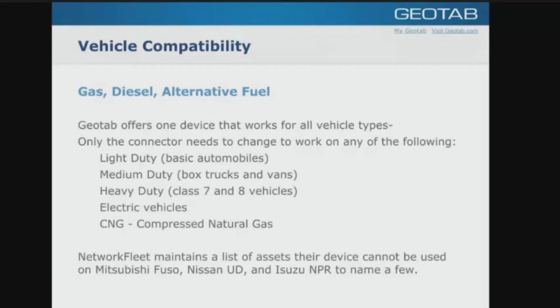These Japanese makes down here at the bottom, Mitsubishi Fuso, the Nissan UD, and the Isuzu NPRs and all the flavors of the Isuzus, they're Japanese-built vehicles. They talk in a different language. You have to decode that language to get that information. We have found, and Carrie, correct me if I'm wrong, it's the Fuso that needs a separate harness to get the odometer? Yep, that's correct.